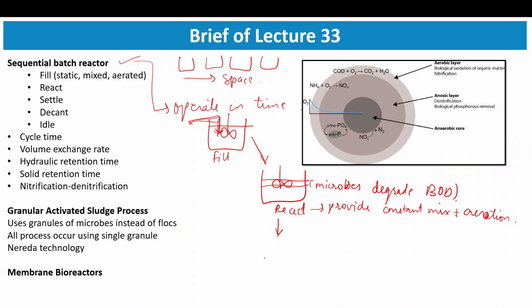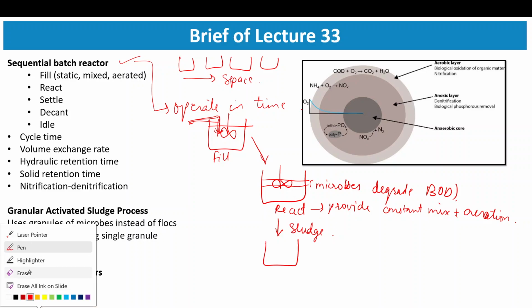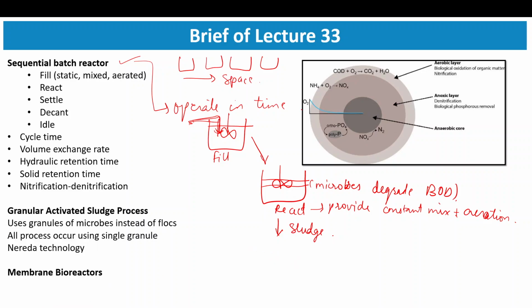Okay. After that, sludge is formed during the reaction. So for that, you provide settling inside a settler for microbes or the sludge to settle down. So this is nothing but a settler. Here you can provide mild mixing or no mixing, and aeration is not required here.